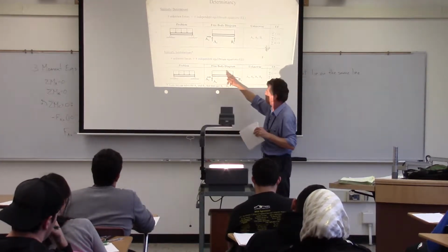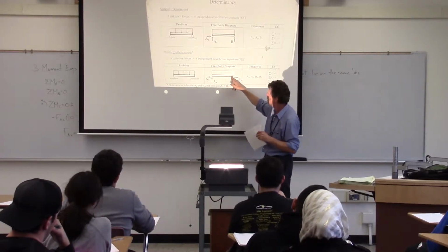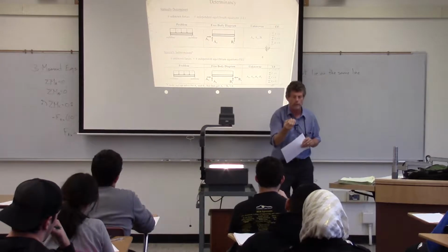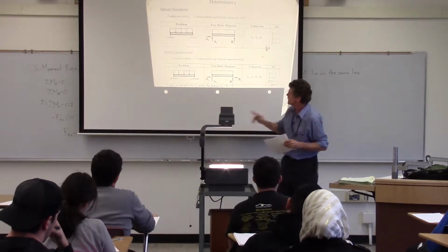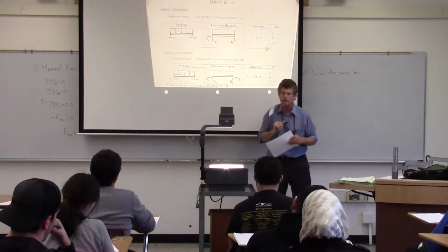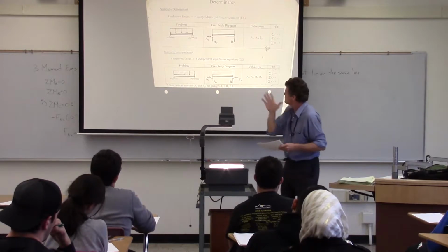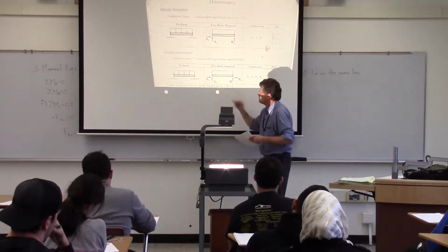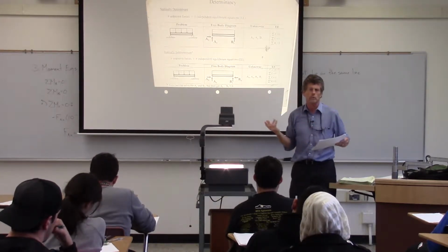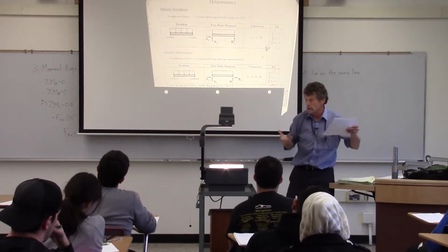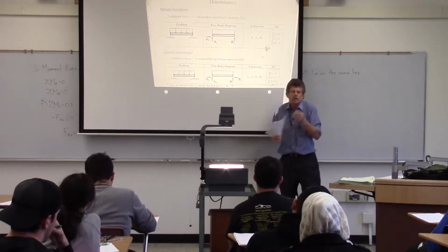I do my second moment equation, and that's why we like these alternative forms. I can go over to B, note that AX goes through B, but I can solve for BY, or AY. So I can solve for the 2 vertical components, and then my last equation be sum of forces in the x direction since they lie in that x-axis there. The best I can do is just note that AX plus BX has to equal 0. I don't know whether they're 0, they might be 100, whatever. But the key thing is I can get some information out of it.